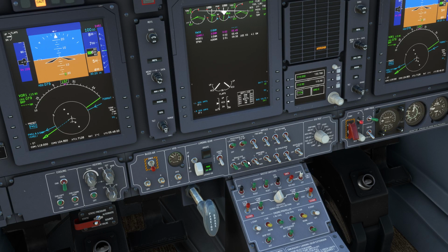on low. Now when it comes to main wings, I do set it to auto, and boots to auto. At this moment I'll leave the forward wings and engine ice vanes to on. The oil cooler intake I'll leave off, and forward wing I'll leave off. Stall warning. Stall warning. Check. Flap system.